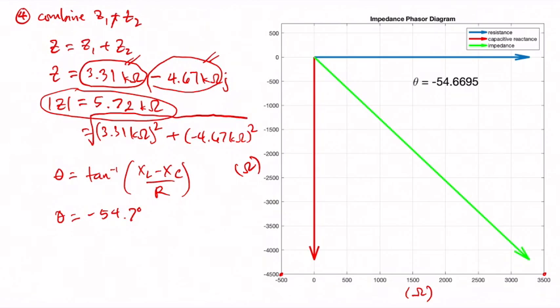Because graphically you draw multiple vectors and you don't want all those vectors to touch from head to tail. So this is why the length of the arrow does not correspond to 3.31 or 4.67 as it should be, and that's only because the command quiver does not draw the arrow to its full magnitude. Okay, but you can check for yourself that the mathematical answer is correct.